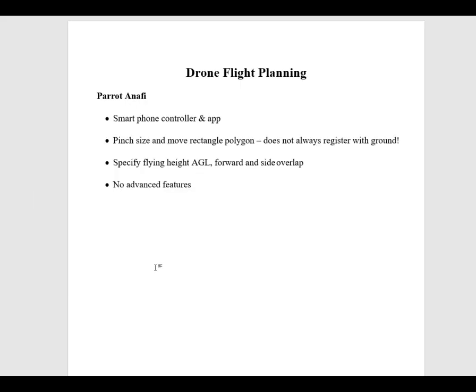Okay, so the drone flight planning, the Parrot Anafi, it just uses your smartphone with an app on it. You pinch and size and move a polygon around. It doesn't always register well with the ground. I did a little project where I centered the rectangle on my project, and then it actually only flew about half of the project. So I had to stop, move the rectangle, and fly. I think it was about the third flight before I got it right. Don't have that problem with the other drone.